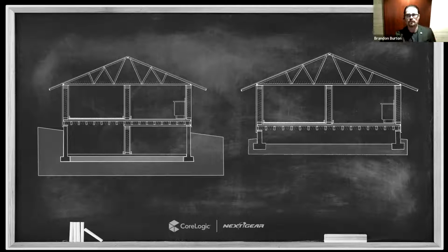This creates a lot of unique challenges, predominantly because we're dealing with a below grade structure. We're dealing generally with a very, very different range of temperatures across the building materials that are in contact with the outdoor environment, that will not be typical of what we're seeing in the living space up above. And in addition to that, those building materials themselves are also generally going to be different.